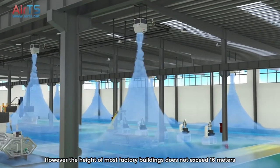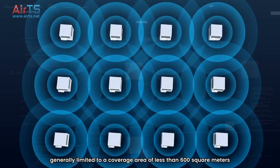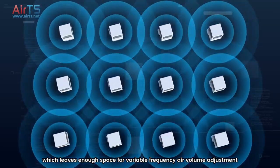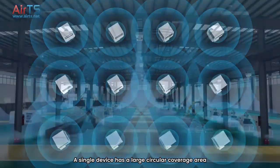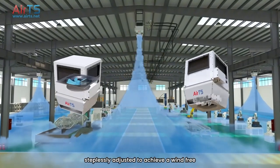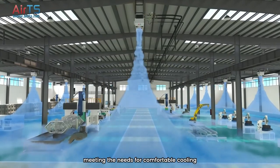However, the height of most factory buildings does not exceed 16 meters. Due to the maximum cooling capacity, the coverage area is generally limited to less than 600 square meters, which leaves enough space for variable frequency air volume adjustment. A single device has a large circular coverage area, and the air volume and air supply angle can be steplessly adjusted to achieve a wind-free feeling on the ground and a more balanced temperature, meeting the needs for comfortable cooling.